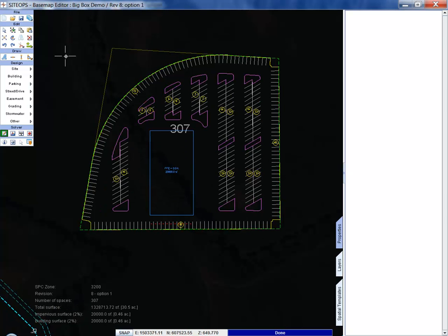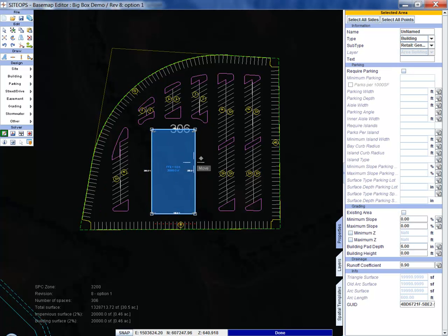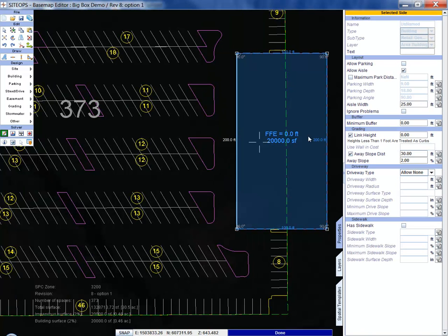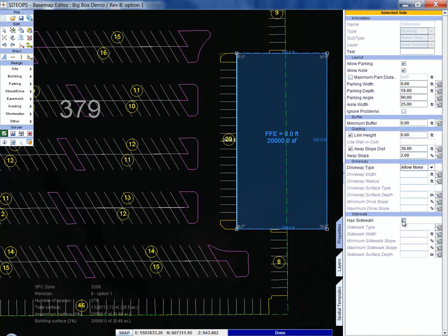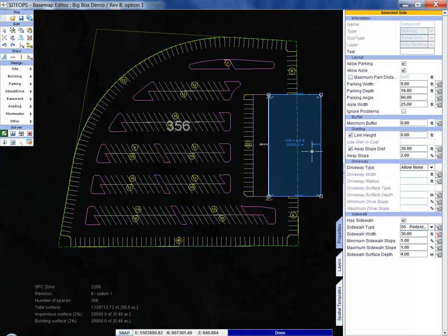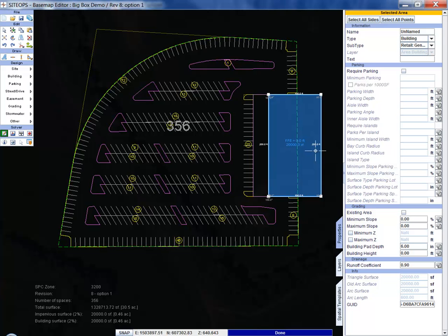see how that reacts. Instantly, the parking moves away. And if you notice on the right hand side, the properties for the building are completely different than they are for the parking lot. Let's say we want sidewalk. Let's come in and make it a little wider so we can put in some tables for a restaurant. Then the client asks for just something simple. Let's come in, let's rotate it, and let's move it along the southern property line.